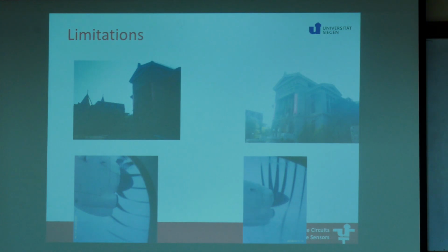You will see at some point of time, the wings of the fan will start bending. And the reason that happens is because of the problem of rolling shutter. Remember, when we are taking an image, we read one row. And in one row, we start from the first column. We convert to digital, take the output, convert to digital, take the output. By the time we have reached the last row, we had assumed the scene has not moved. But if the scene starts moving, so here in this case, these wings, they moved, and you can see what has happened. We have got this shearing pattern here.